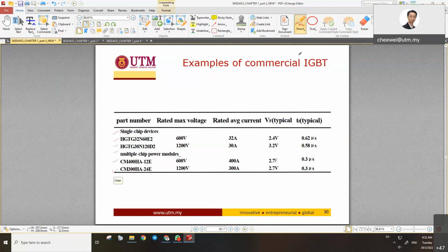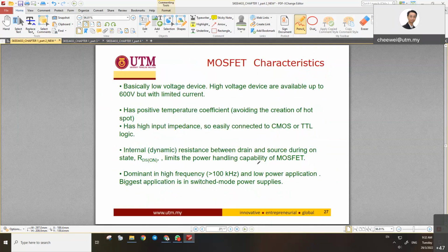Okay, for example an IGBT, if you want to buy, let's say, then you go and see the voltage drop. Which one is better here? Do I buy 3.2 or 2.4? You can select. If you want high losses, then you buy the high losses. If you want to design a good efficiency system, you need to survey until you have maybe 1.0 volt. This is not all the manufacturer options, right? You can go and survey more.